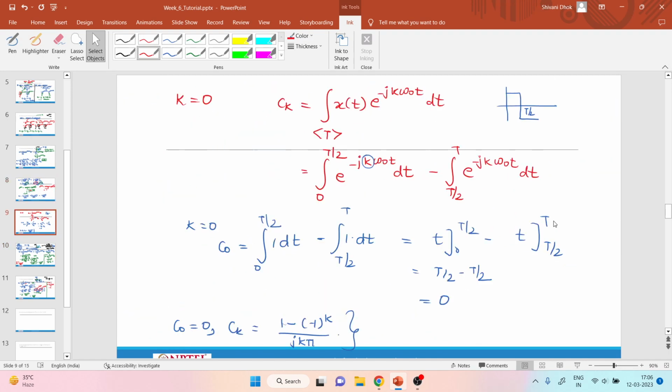If you observe this equation here, this signal is looking something like this, right? It has one fundamental frequency and so on, but actually this square pulse is constructed using multiple complex exponentials or multiple sinusoids, which have non-zero amplitude only at some particular values of k.